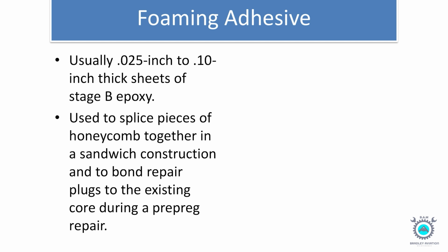Foaming adhesive, usually 0.025-inch to 0.10-inch thick sheets of B stage epoxy, used to splice pieces of honeycomb together in a sandwich construction, and to bond repair plugs to the existing core during a prepreg repair.